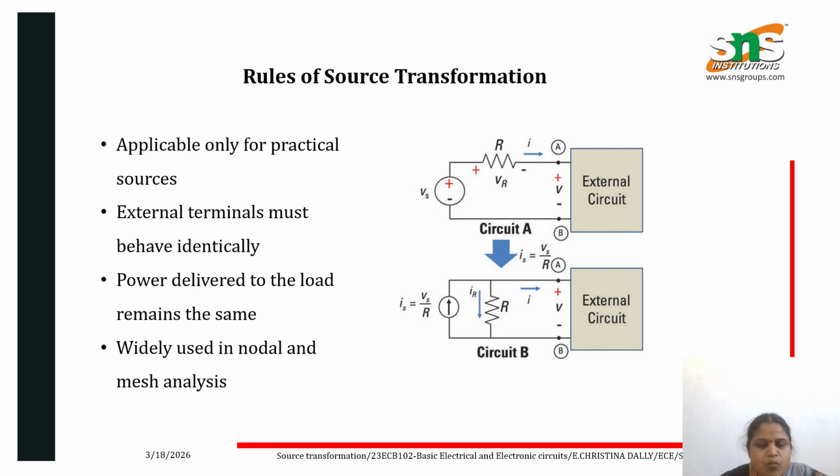We are going to see the rules of source transformation. It is applicable only for practical sources, and the external terminals must behave identically. The power delivered to the load remains the same. It is widely used in nodal and mesh analysis.